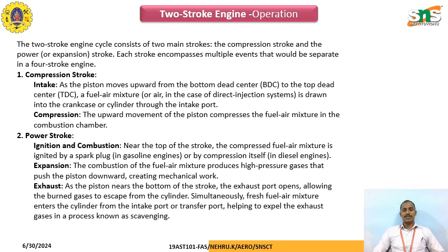Expansion: the combustion of this fuel-air mixture produces high pressure gas that pushes the piston downwards, creating mechanical work. Exhaust: as the piston nears the bottom of the stroke, the exhaust port opens, allowing the burned gas to escape from the cylinder. Simultaneously, fresh air-fuel mixture enters the cylinder from the intake port and transfer port, helping to expel the exhaust gas, in a process known as scavenging.